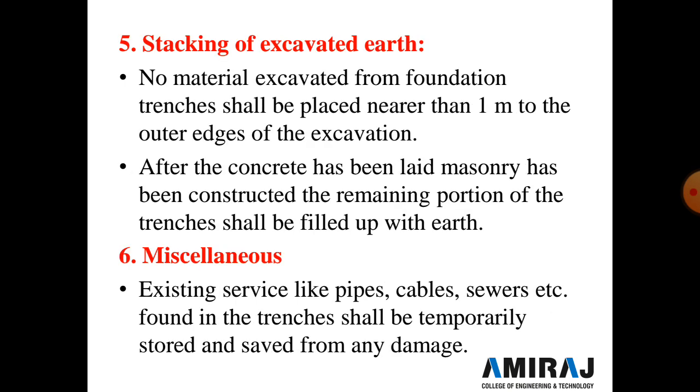And the fifth one is stacking of excavated earth. Normally no material excavated from the foundation trench shall be placed nearer than 1 meter to the excavated area. After the concrete has been laid and masonry has been constructed, the remaining portion of the trench shall be filled with earth in layers of 15 centimeters, watered and well rammed, and the surplus excavated material shall be spread out uniformly up to a lead of 30 meters.